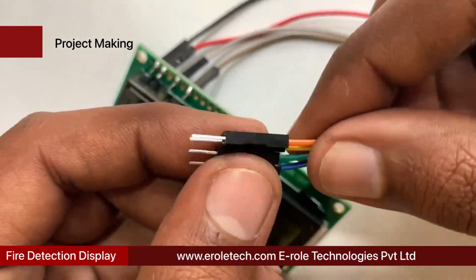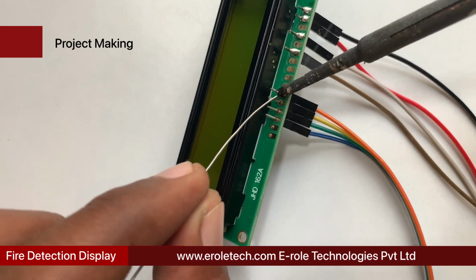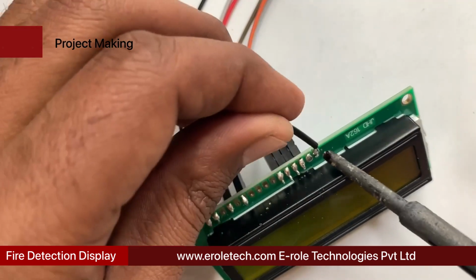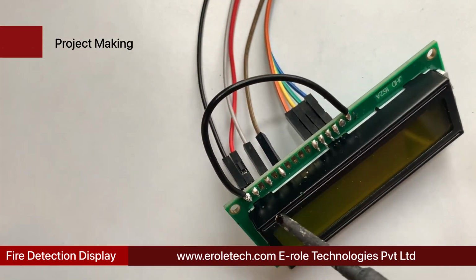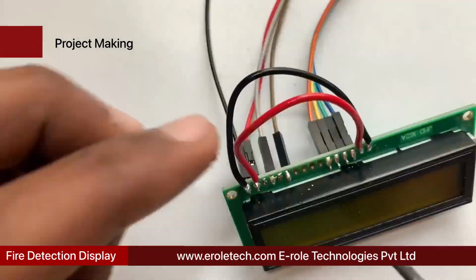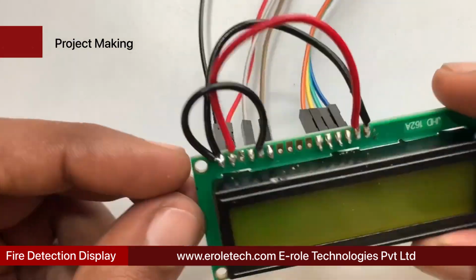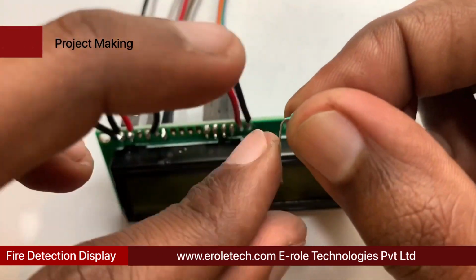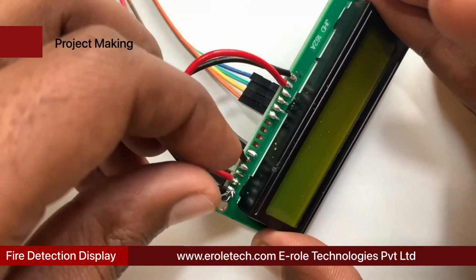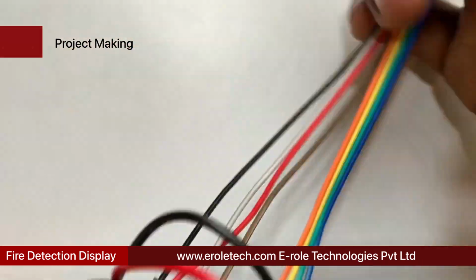Now we will solder orange, yellow, green, and blue wires at pin number 11, 12, 13, and 14 of LCD display. Now connect hole number 16 with hole number 1 using a black wire, and hole number 15 with hole number 2 of LCD display using a red wire. Now connect hole number 5 with hole number 1 of LCD display using a black wire. Now connect hole number 3 with hole number 1 of LCD display through a 1 kilo ohm resistor.